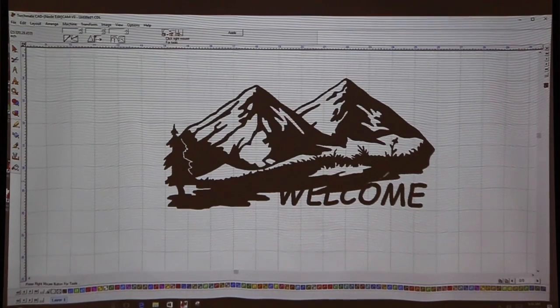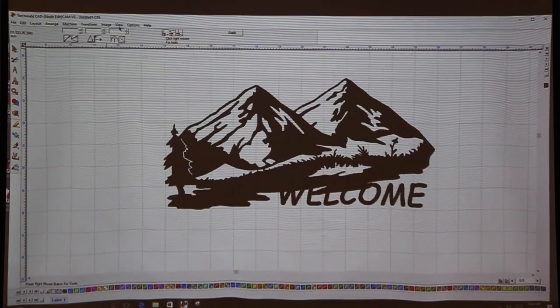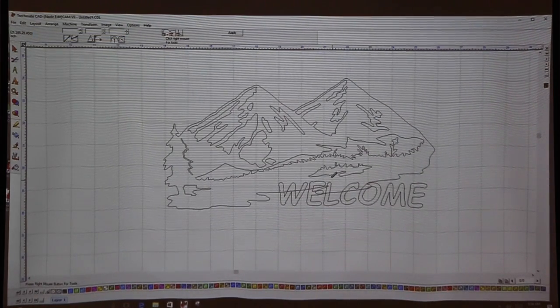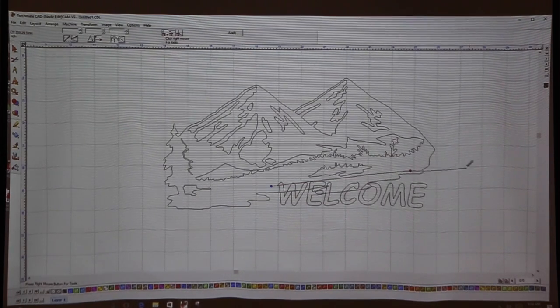In order to make our blob shape, it usually is helpful to get out of fill mode. So I'm going to go to View, take off Show Fill, and it gives us a better idea of what we are working with. Now the way the arc edit tool works is that it's just a left click and then it starts with a line. Now we can just do straight lines by just doing another left click. And as you can see, it generates this next line.